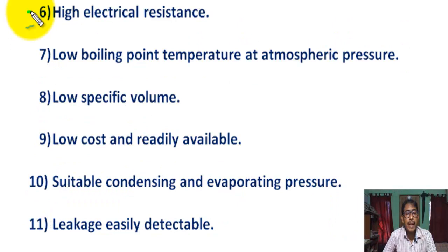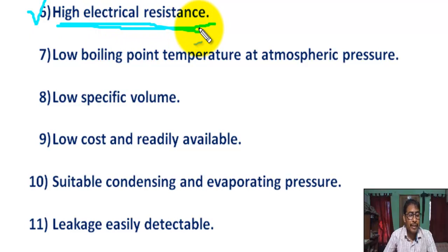Number 6, a refrigerant must be high electrical resistance. Dielectric strength of refrigerant is an important property in hermetically sealed compressor, as the motor windings are cooled by refrigerant vapor on the way to the suction valve of the compressor.